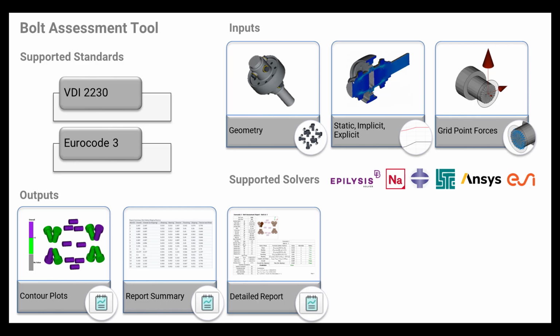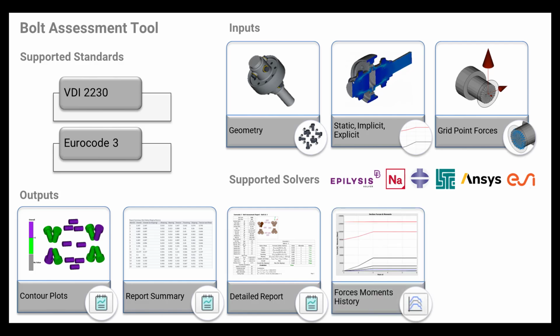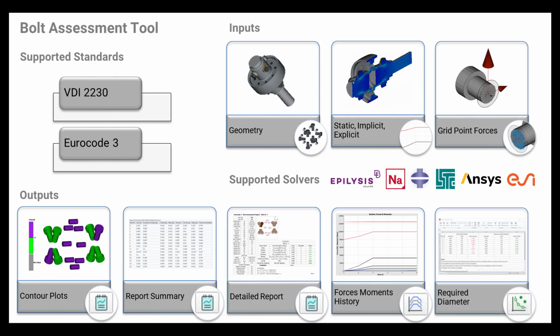Moreover, detailed reports with analytical hand calculations can be generated in PPTX or XLSX format. Additionally, the full history of the bolt's internal forces and moments can be created to give you insights about the loading condition of the bolts. Finally, algorithms determining the required bolt diameter and class to prevent failure have been implemented.